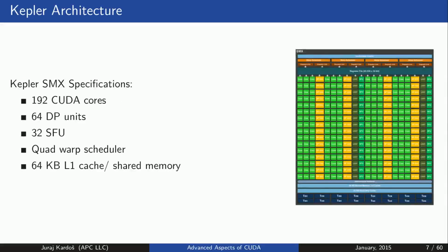The Kepler architecture employs a new streaming multiprocessor architecture called SMX. Kepler reduces the amount of control logic and increases the number of CUDA cores 6 times when compared to the Fermi streaming multiprocessor. Because all the Kepler CUDA cores run at a lower clock speed than in Fermi, the GPU as a whole uses less power even though it delivers more performance. The primary focus was put on energy efficiency, resulting in the fact that 2 Kepler CUDA cores consume 90% of the power of a single Fermi CUDA core.